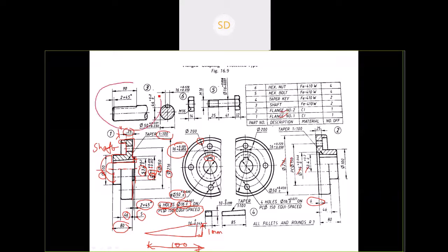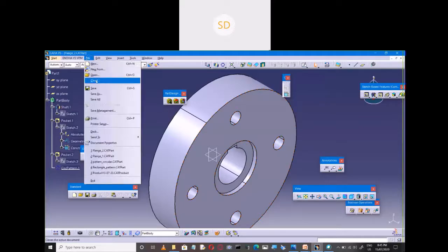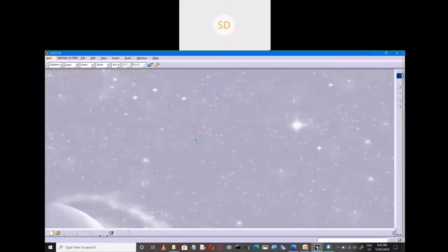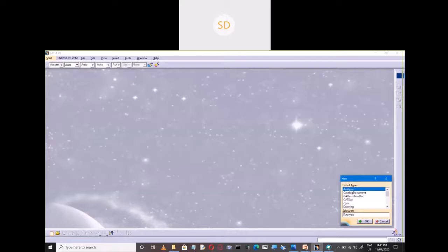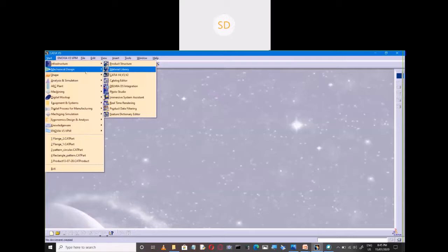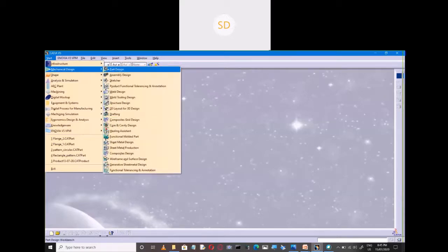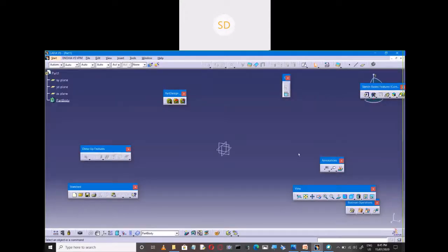Now you need to go for a shaft here. It has a diameter of 50 mm. Now you can make the shaft by using a revolved protrusion, which is what we call a shaft in CAD. Otherwise, you can go for the pad option. That is also possible. You just draw a circle and extrude it. So I'll go first with a pad.